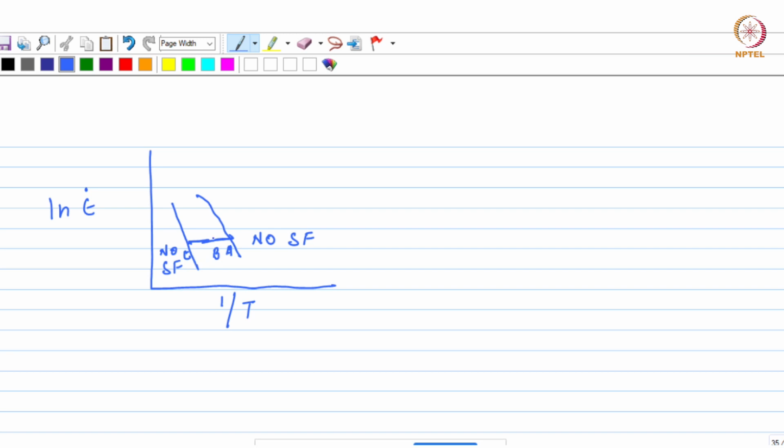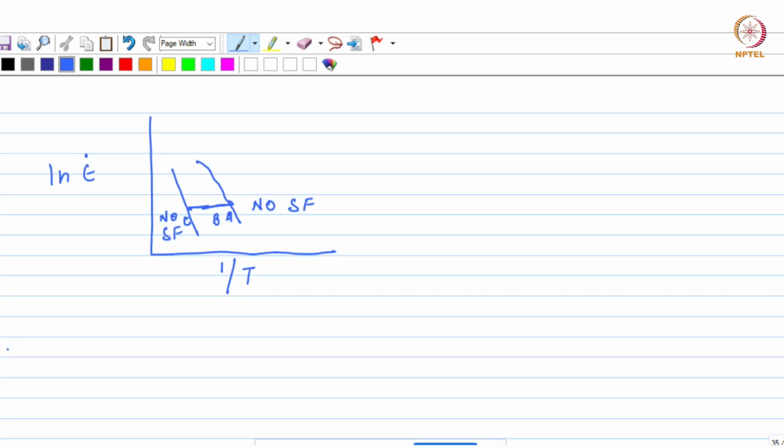Okay, and you can also see that as you decrease the strain rate, you would have the same change from A to B to C. Okay, so with decreasing strain rate also, it changes as A to B to C. Number 5, this we have already seen that serrated flow is always associated with negative strain rate sensitivity.